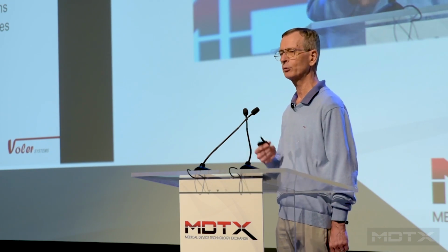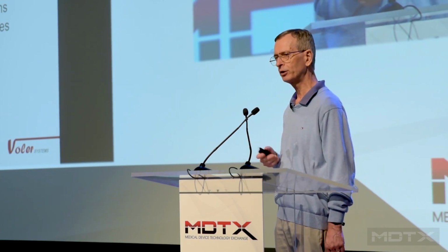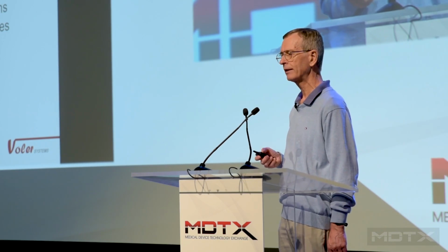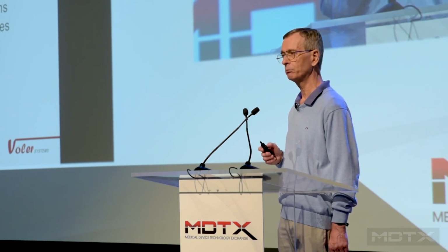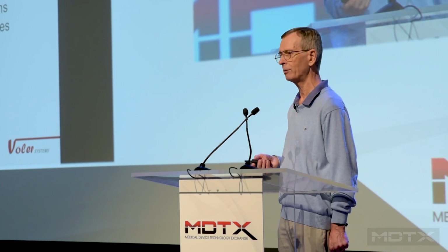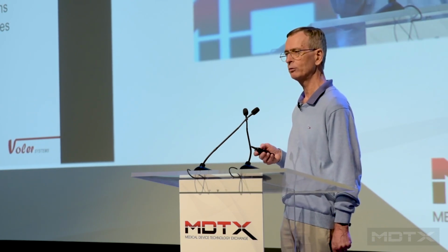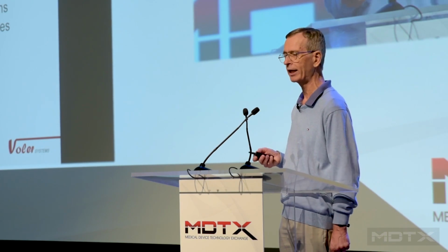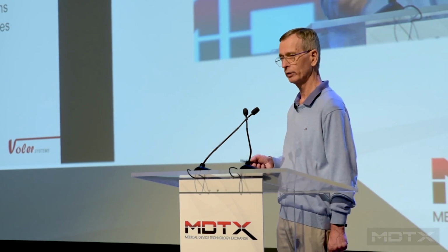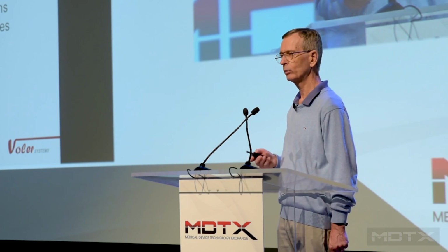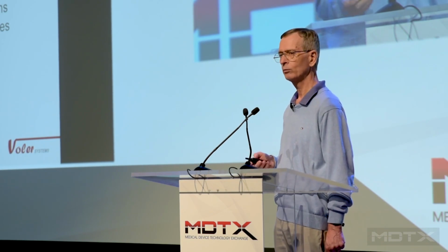It sends the infrared light into the body and looks at what's reflected. The amount that's reflected is quite small, so the accuracy isn't as good, but it works on virtually any place in the body. And the problem with accuracy is nobody's achieved what would be considered medical grade accuracy with a pulse oximeter with the reflective type without calibration. And how are you going to calibrate it unless you have the transmissive type?